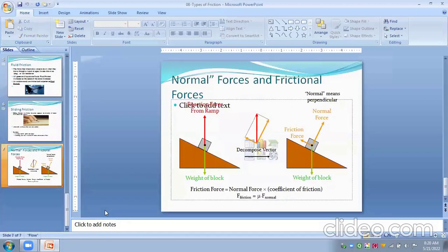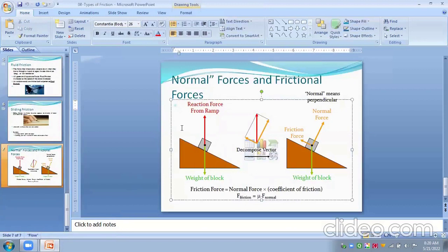Here we are seeing the inclined plane rig on which we determine the friction. A specimen is placed on a flat plane whose inclination with the horizontal is gradually increased until the specimen on it starts sliding, and the angle of inclination theta at that moment is measured.